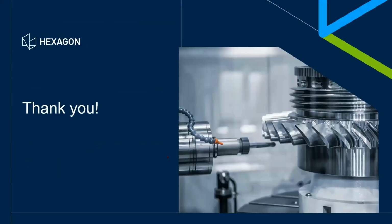So now we have seen so far about the ESPRIT EDGE new features, what is available, and how it is going to help them. As I mentioned in the first slide, we have different 5-axis strategies, like channel, swath, and the impeller. I will show some workflow and the ESPRIT EDGE files, so that you can easily understand how easy it is to create the programming, and how you easily achieve the expected toolpath through these option features.